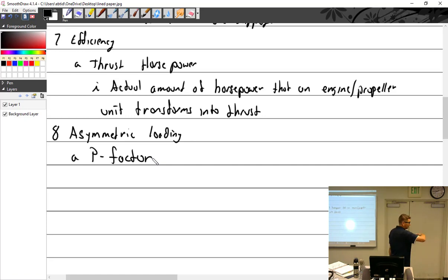So what happens? That tail comes up. You've got to be ready, and you've got to give it right rudder, and then left, and right, and left, and a little right and a little left, and you just dance on them until it's time to go. But it's really important that you bring in that right rudder to keep the airplane from going off that way.